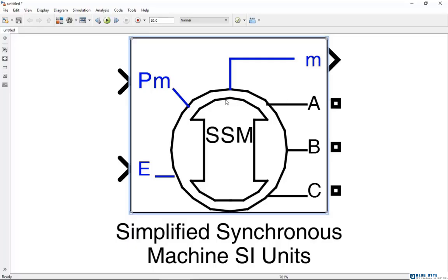By using this block, we can transfer the electric part, and for the general part, for example, we can specify its mechanical power by a constant number. For example, we can define its excitation voltage with a constant number. The M output is the synchronous generator data, which we can show with the mux block. So as you saw, there are some blocks which deal with both specialized and Simulink general signals. These blocks can be a suitable connector in those libraries that want to use them.